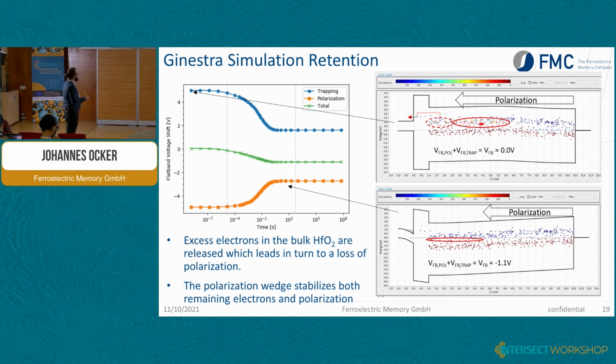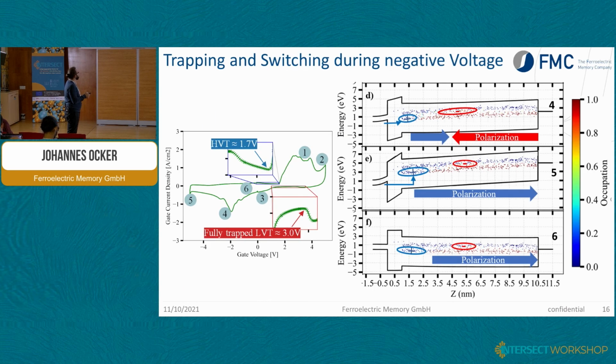Because in the simulation before, for the erase pulse, we also showed that we cannot completely get rid of all this negative charge during one program and erase cycle. So it is kind of stuck, and with repeated cycling the negative charge will just accumulate.